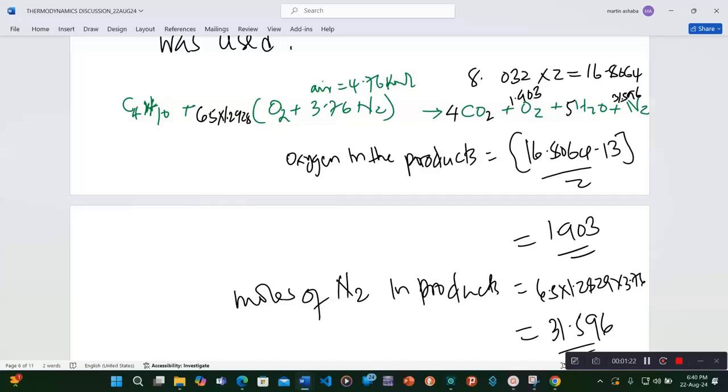And then because we have excess, remember we have used the air fuel ratio of 20, we have an increase by excess air of 0.2928. 0.2928 is added onto the original existing air, which was 1 by proportion. So when we add it to 1, we will have 1.2928.